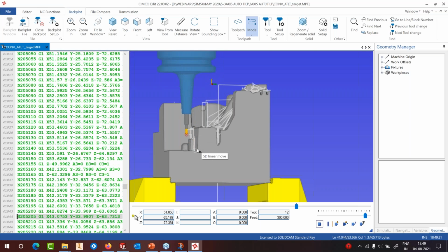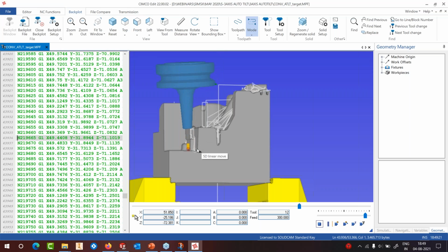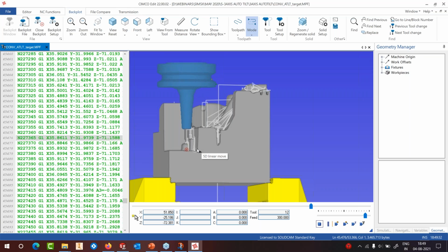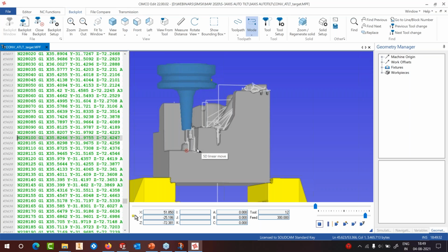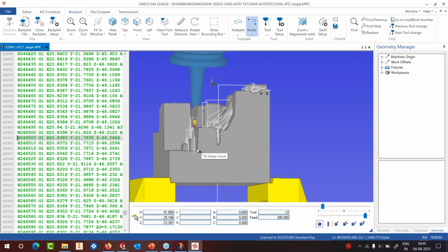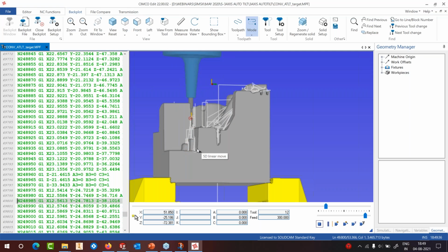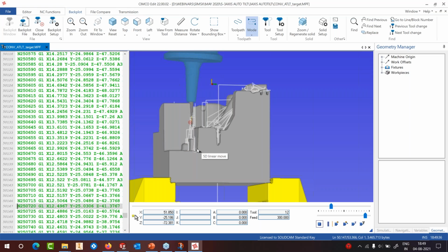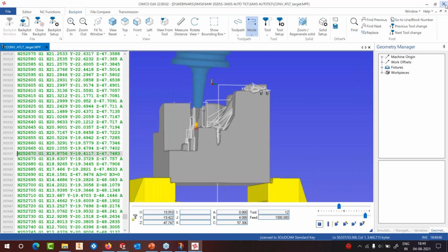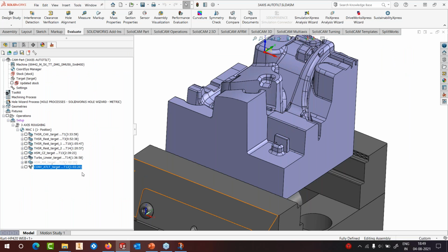So you can actually take any 3-axis tool path and just convert it to 5-axis without breaking a sweat, breaking anything. All you have to do is to define a proper holder and ensure that the similar setup is also on the machine. Okay, so you can actually do both rest roughing, and finishing tool paths. You can convert it using the SolidCAM 5-axis conversion functionality. Right, let's go now into our final 2 parts.